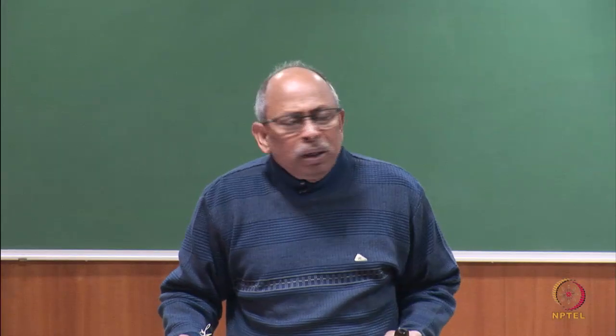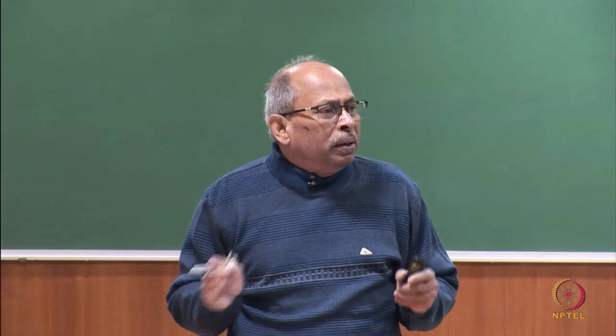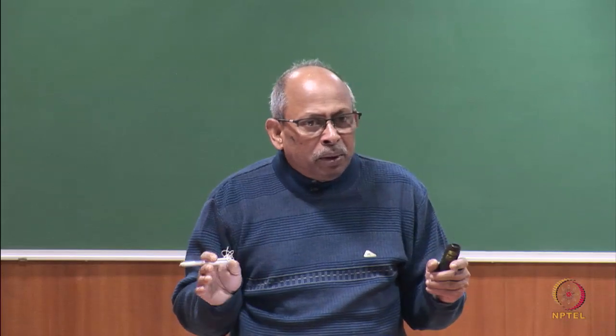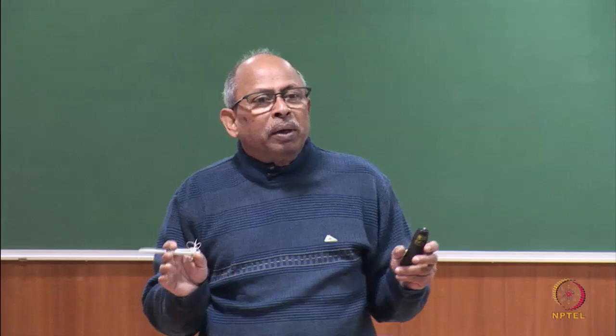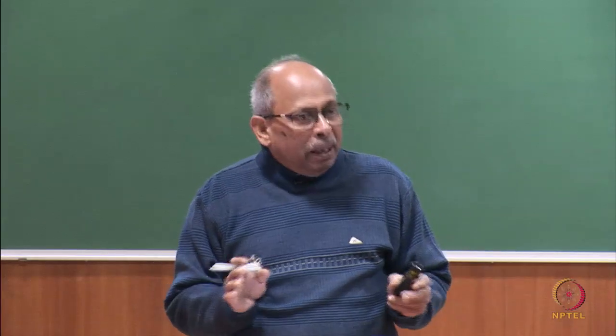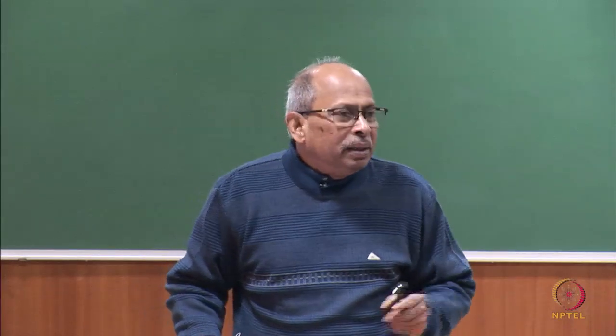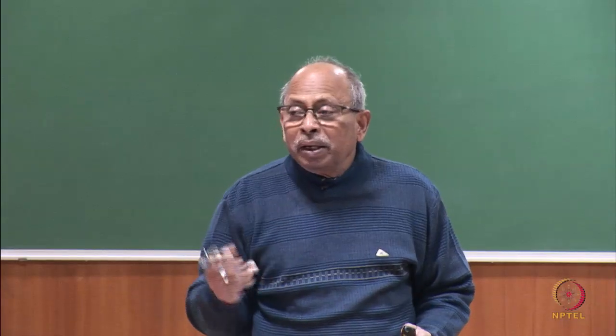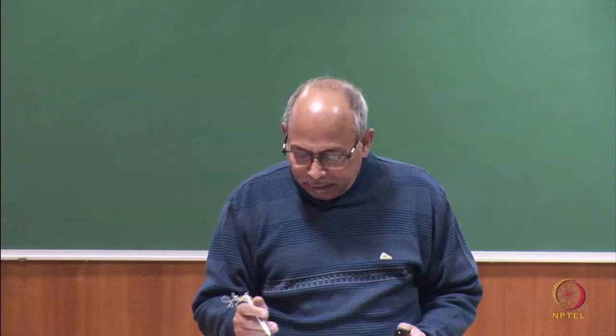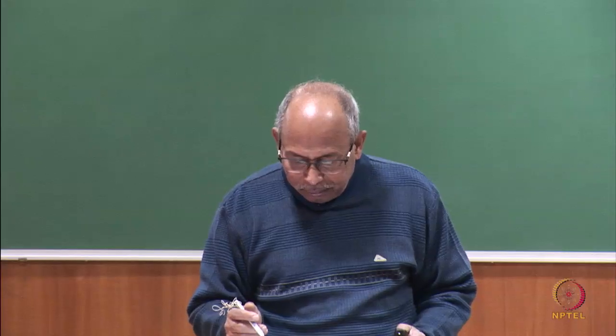In engineering economics, when you have 2 projects you want to compare, you have what are called planning horizons. For buildings, normally our planning horizon is 60 years. So, if you are doing repair twice, your grey energy is more and so on. So, that is the importance of this.